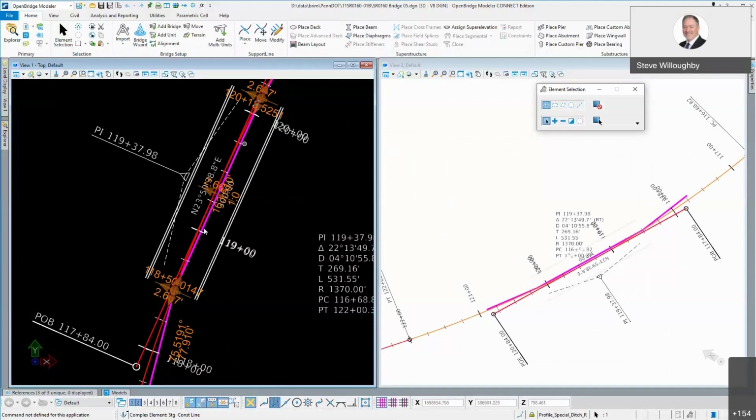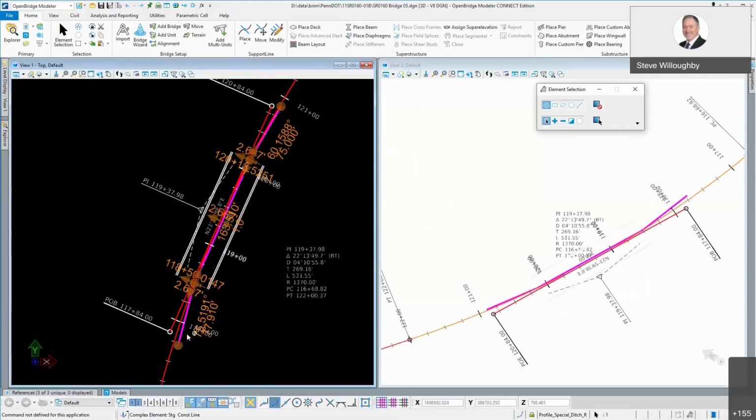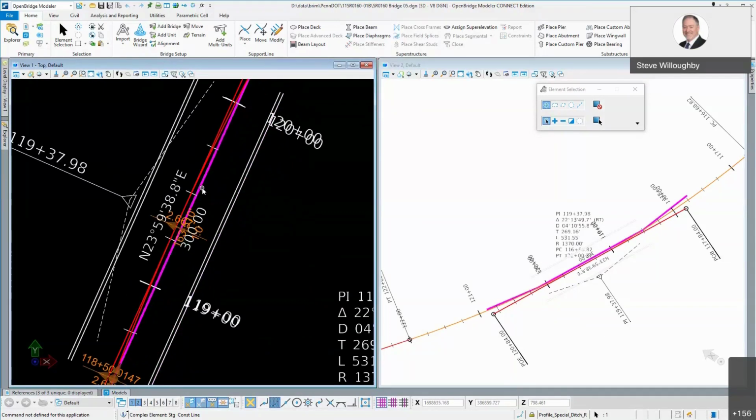And initially I started with just that little piece of line right there. Now you'll notice if I zoom out, there's actually 3 lines here. There's another extra line here and an extra line up here, and I'll get to that in a moment. But initially I started out with just the first piece there. And then once I knew that line, I took that line and copied it parallel to represent my edge of deck on each side.